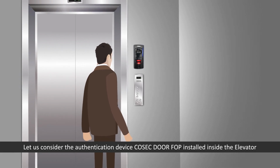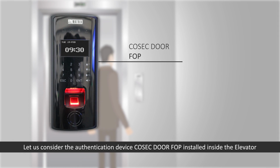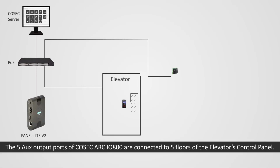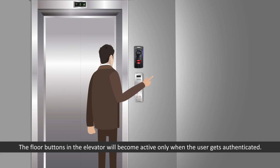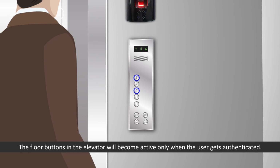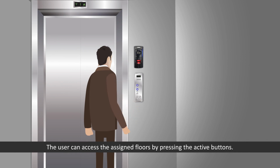Let us consider the authentication device COSEC Door FOP installed inside the elevator for authenticating the user. The 5 aux output ports of COSEC ARC IO800 are connected to 5 floors of the elevator's control panel. The floor buttons in the elevator will become active only when the user gets authenticated. The user can access the assigned floors by pressing the active buttons.